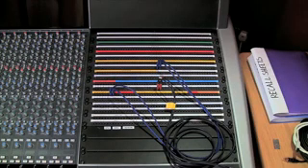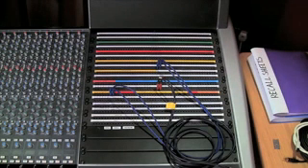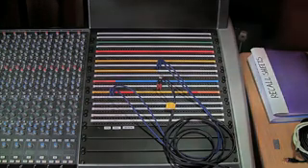Patchbays are set up to automatically send signals from the top row to the bottom row. Outputs should be set up on the top row and inputs on the bottom row. Patchbays can be configured in 4 different ways, depending on your studio equipment and workflow needs. And these 4 modes are normaled, half-normaled, parallel, and open. Changing the way a patchbay is configured can be as simple as changing the switches on the top of the patchbay if your unit comes with them, or breaking out the soldering iron if not.